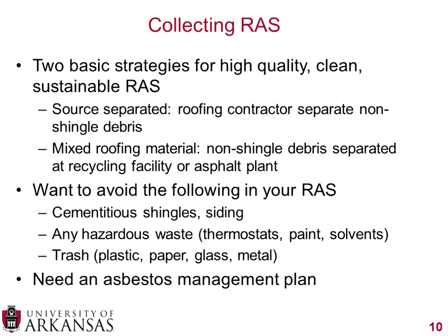So you're looking at adding about 1% asphalt cement to your mix. So if you have a 4 to 5% asphalt binder content, that is a potentially 75 to 80% virgin binder, and then 20 to 25%